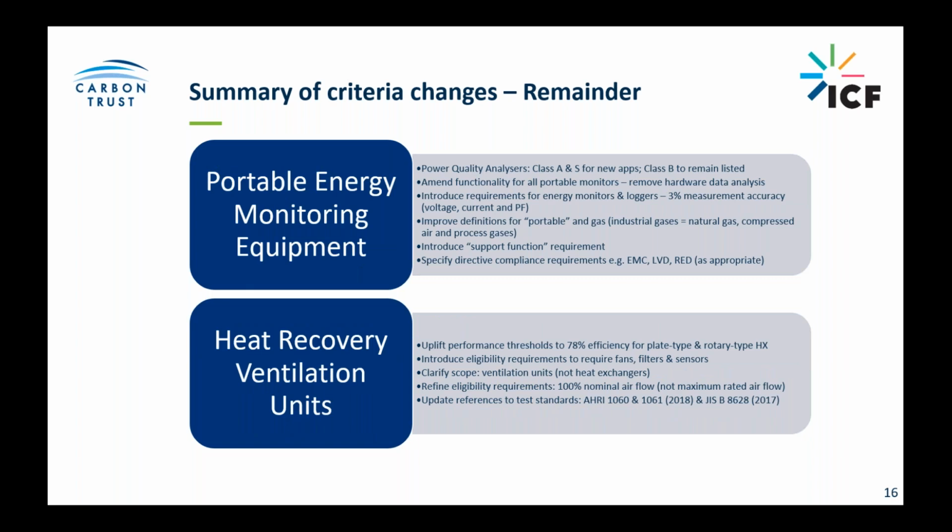Portable energy monitoring equipment, quite a few changes here. So for power quality analyzers, we set performance thresholds. We've amended the functionality requirements for portable monitors, removing hardware data analysis, which is now not being used. It's all software based. We've introduced requirements for energy monitoring loggers, around a 3% measurement accuracy requirement.